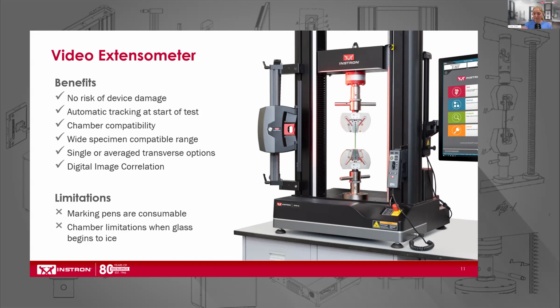If you want to take this analysis one step further, using digital image correlation, a full field strain map can be generated after a test, and that can be synchronized back with your data from Blue Hill Universal. Oftentimes, I see this in research and development environments, and DIC just acts as a really powerful tool to help labs understand what's happening in various regions of the specimen during a test, aside from maybe just what you see with single point axial tracking traditionally.